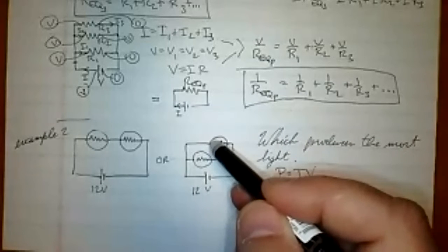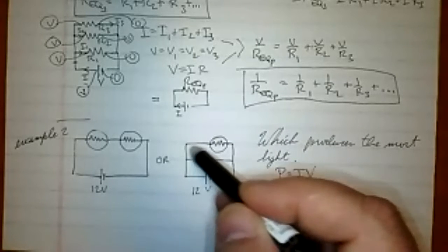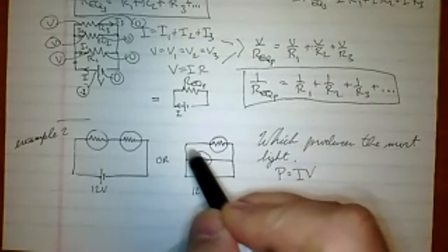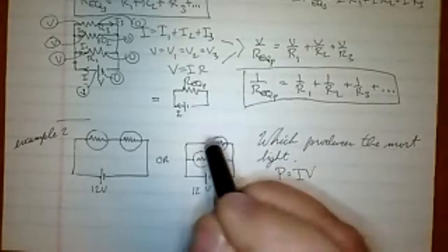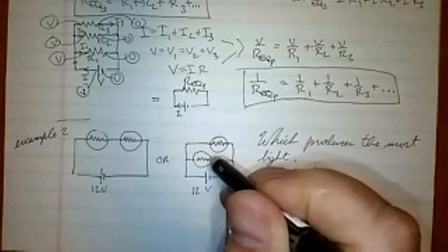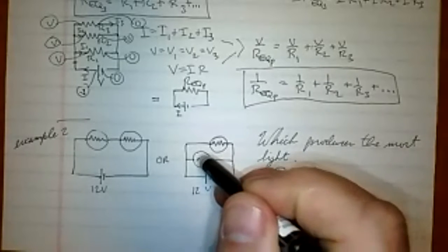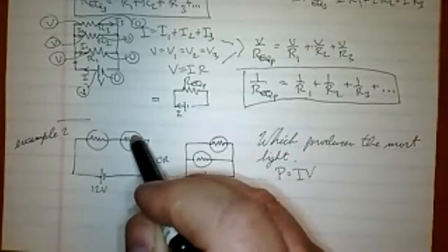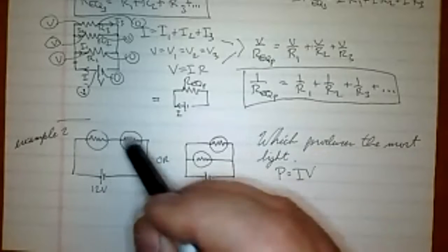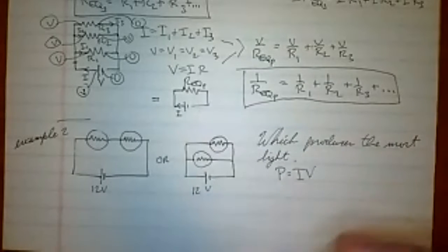So clearly the net resistance of this one's smaller. So the total current coming out of here would be larger, even though you are going to divide each current by 2 for what each light bulb gets. I just became Elmer Fudd or something there. This one, on the other hand, is going to have a bigger resistance, but each one's going to get exactly the same current.